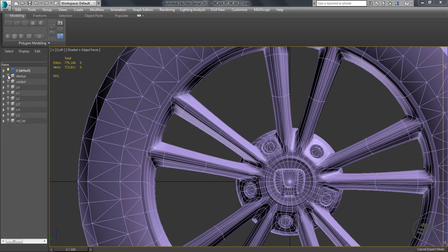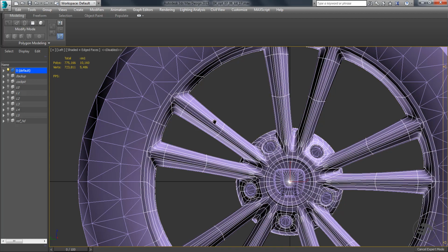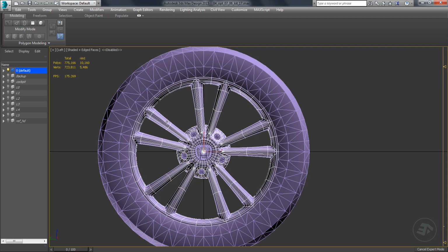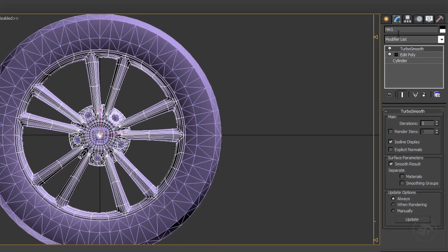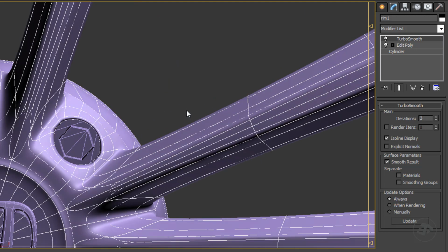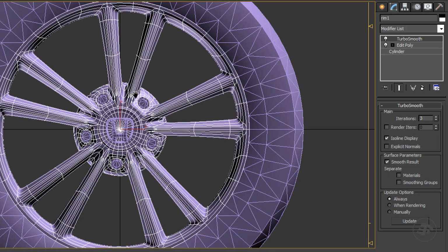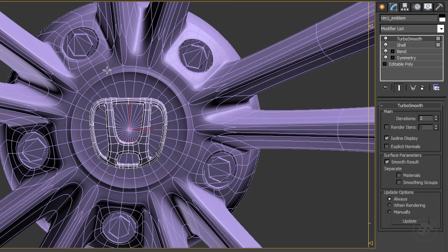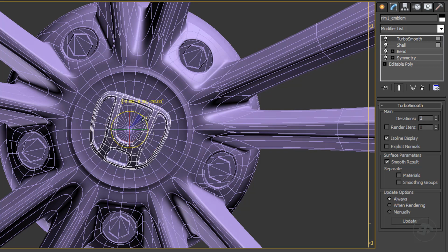We are going to use the high detailed rim that we have created in the previous video, with 3 iterations in Turbo Smooth modifier options. A very high and smooth detailed 3D object is required specifically to capture a smooth texture, pixel-wise. I am going to project the details of this model with 2 different UV maps in order to create 2 different materials. One for the first level of detail, and the other for the lower levels.